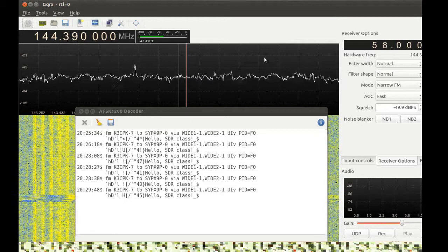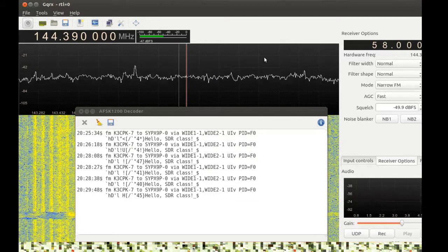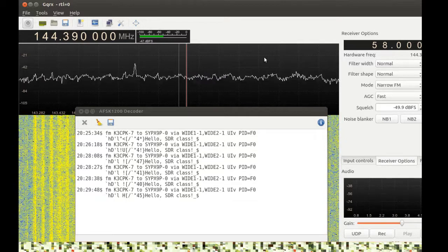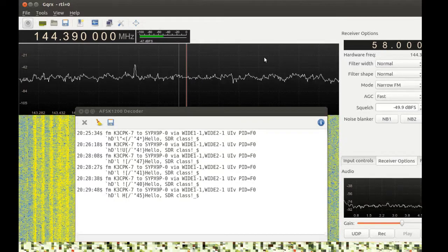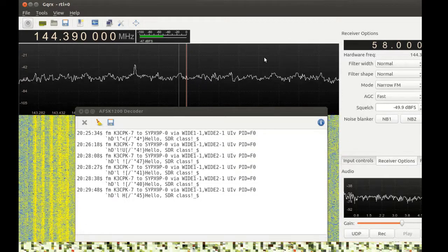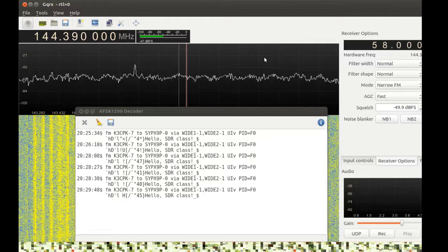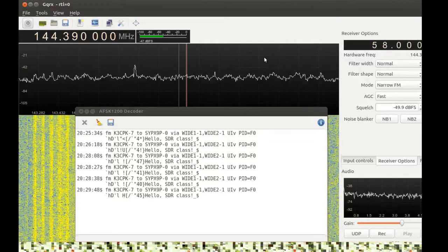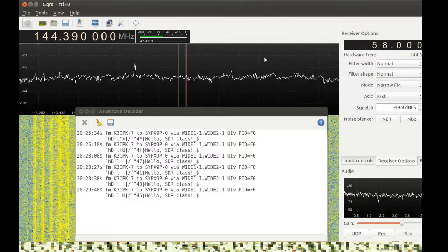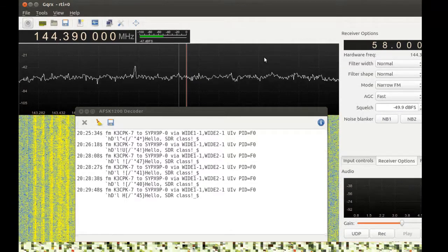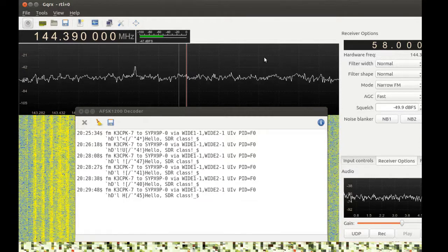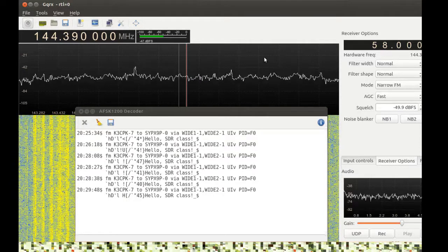I'm seeing the signal, it's definitely there, but my AFSK decoder is not decoding. I definitely see a peak. Your FFT size looks fine. Close the PulseAudio volume control in FLDigi, and then I'll do it again. Ooh, your audio was maxed out, wherever you were feeding it into. Yeah, keep that close to 0.